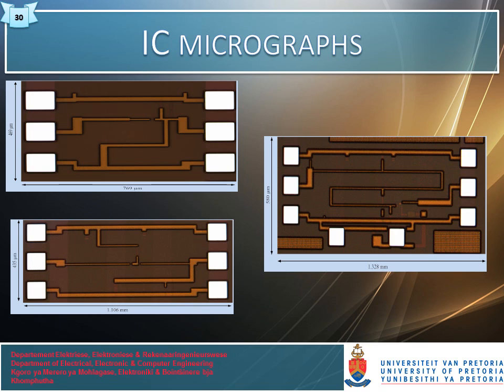The figure on the right hand side is a Butterworth filter, and the presence of the two white pads at the bottom of the circuits act as biasing structures for the buffer circuits to avoid external loading when the circuit is probed.